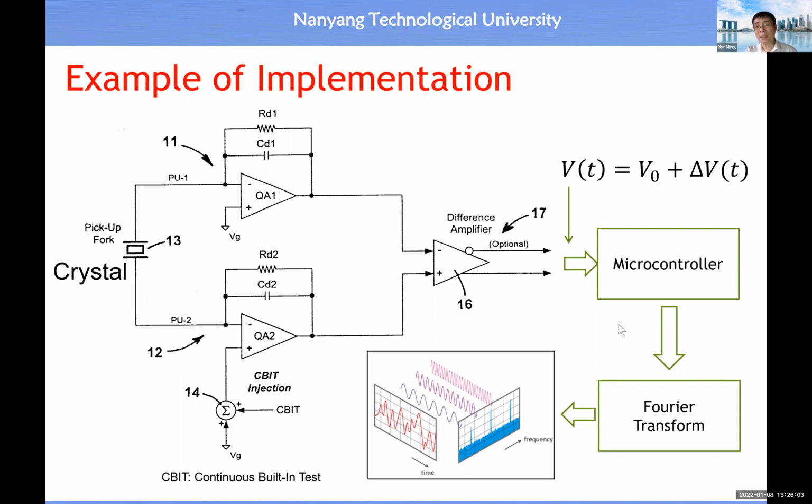This is because the microcontroller can take in the time function as an input, because the microcontroller can run at a high frequency. So it can do the conversion of every value within a very short period of time, because the microcontroller can operate these two operations. One is sampling. Sampling is just to take a sample at the discrete time instance. The second operation is quantization, which converts that sampled value into a digital number. So all in real time, very, very fast. So it's not a problem for us to enter a time function of a voltage into the microcontroller.